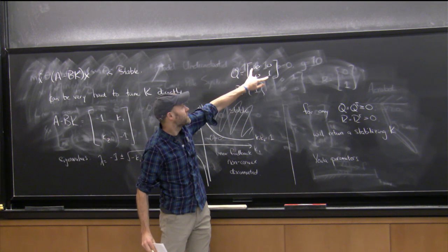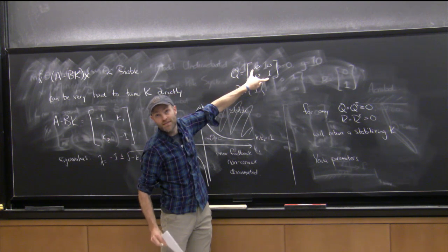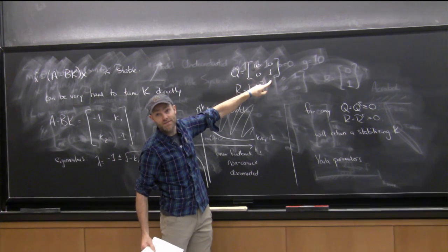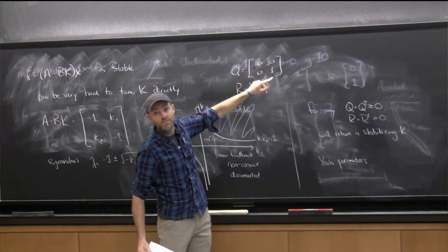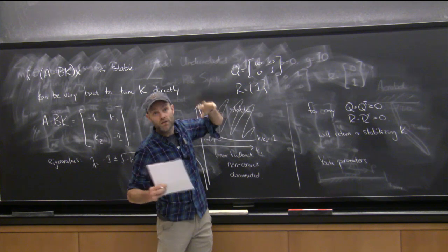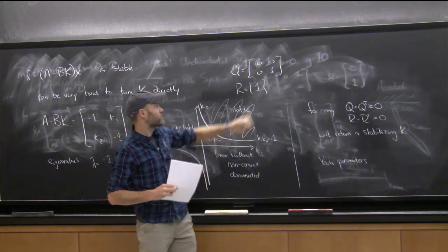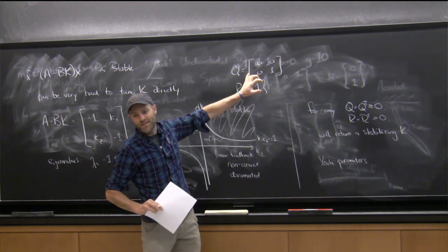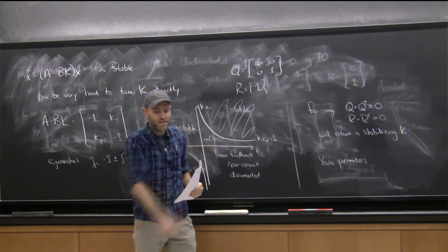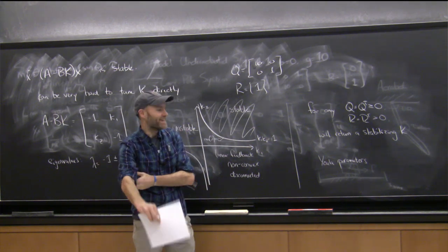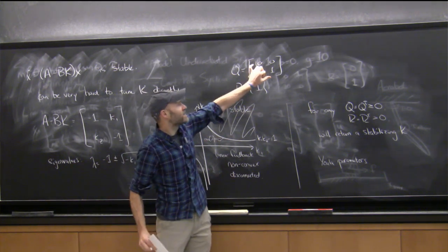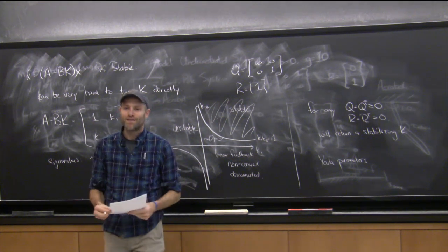Well, it turns out that these things live in different coordinate systems. This is in units of radians, and this is in radians per second. This is multiplying my velocity term. So I tend to try to scale out the units properly, by square root of G over L, if it works through. If you remember nothing else, you tend to have a 10-to-1 ratio and you're pretty good. It works almost always, because everything's about a meter, and gravity's always 10. So it kind of works out, okay? So if you see these 10-to-1s, that's where it comes from. There is some method to the madness.